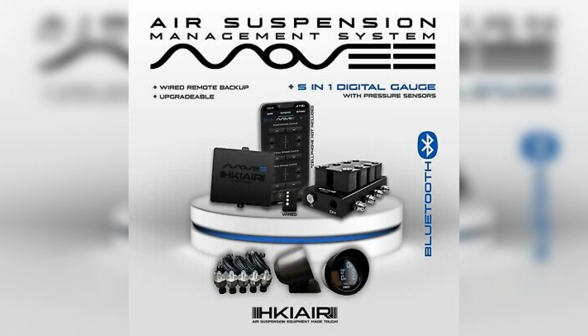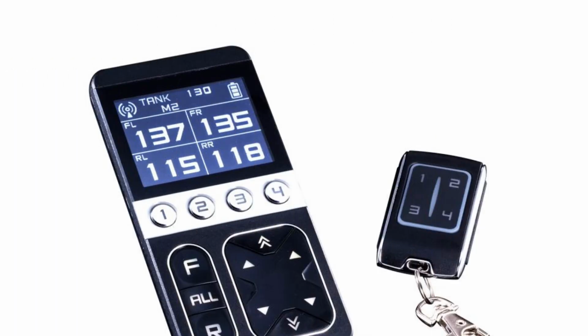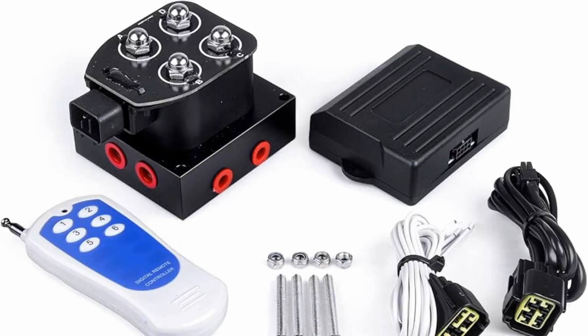Owners of open-type air cushions can be strongly recommended to raise the car more often to the highest position at the car wash to thoroughly wash out sand and dirt from under the cuffs. It is also necessary to make sure that hoses of air lines are not frayed. Air leaks should be repaired as soon as possible, as frequent activation of the compressor significantly reduces its service life. Otherwise, the possibility to change the suspension rigidity and clearance of the car gives not only an advantage when transporting cargo or going off-road, but in general makes the car more versatile.